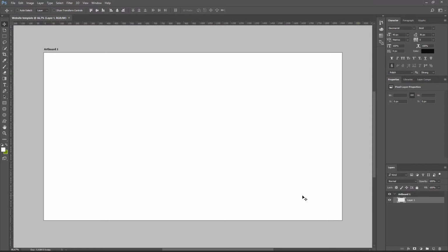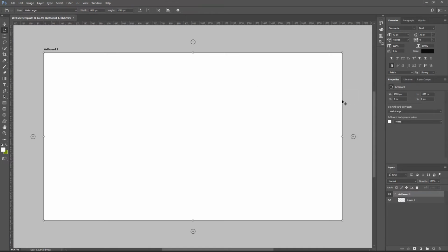To create an additional artboard, pick the Artboard tool or hit V for the Move tool, then click the edge of the artboard and you'll see small buttons with plus signs. Pick one and click it. I tend to go from left to right as this works well for widescreen monitors, but you can choose whichever side you fancy. Once you add the second artboard, you'll want to resize it to your desired resolution.